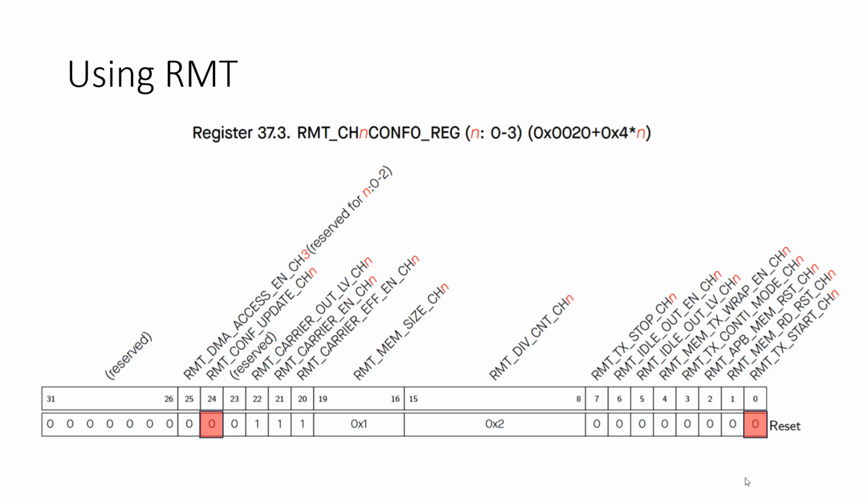And then there's the update. Do you have to call the update after you start? I don't think so. The technical reference says whenever you change anything in the register, you have to set that bit. So I know you had it in there, but I thought maybe that might not have been necessary, because I don't remember doing that last year. But that bit didn't even exist last year. That's a new S3 thing.